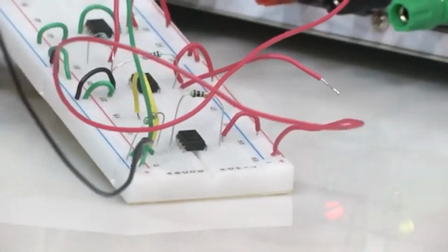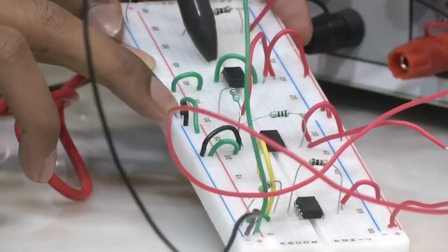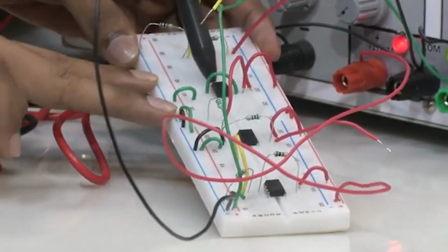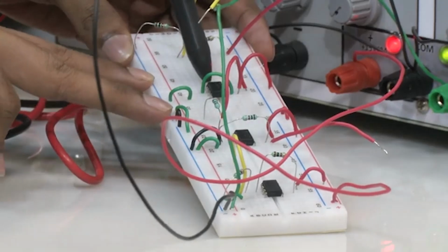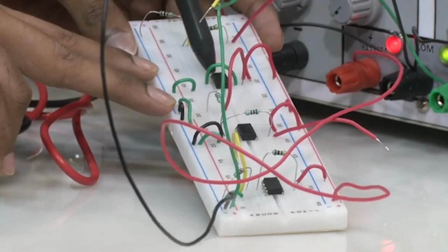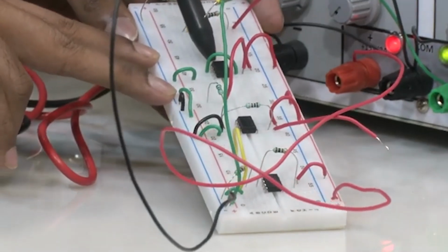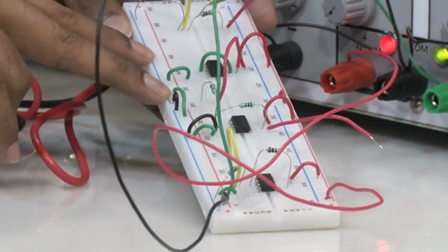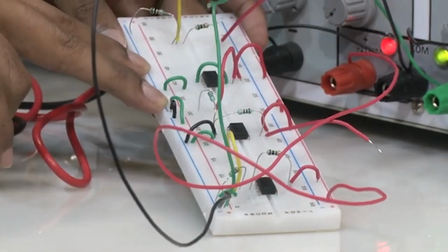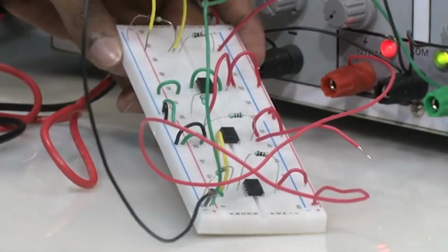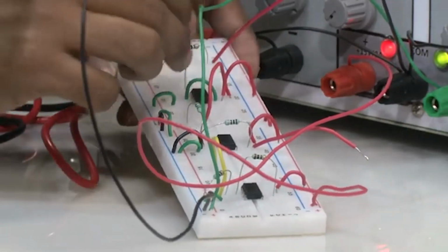You see, this is the buffer circuit, where my pen is. We have seen that in the buffer, the inverting input and the output are shorted and the non inverting input is grounded in the op amp. This is your buffer. So, the output of this potential divider is connected to the buffer. Can you please connect it to the buffer?